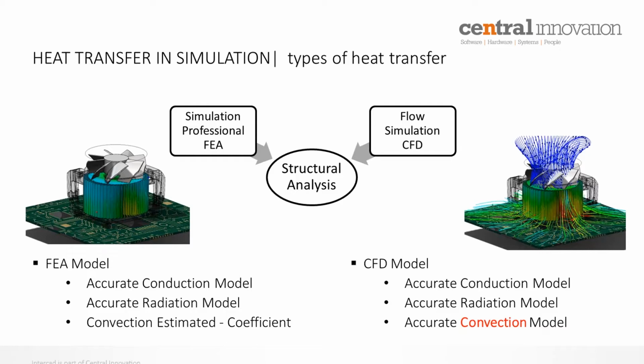However, when heat is transferred through convection, so for example in this forced fan case, where the air will flow out, we need to tell the faces of our solid the coefficient of convection. So this is a value we have to specify, and we have to understand what it is to get an accurate answer. So it's estimated based on our judgment.